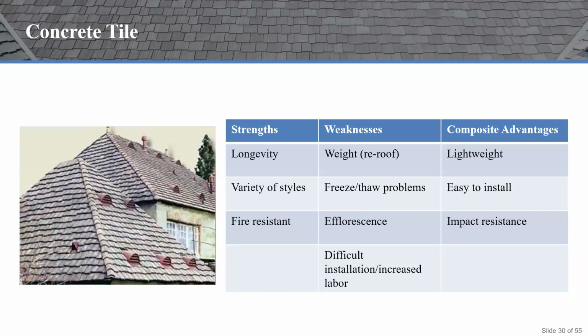So looking at concrete tile, it's established. It does have its longevity strengths. It's available in a variety of styles and sizes. And they tend to be fire resistant as well, right? But from a weakness, very, very heavy. 900 pounds, right, per square.